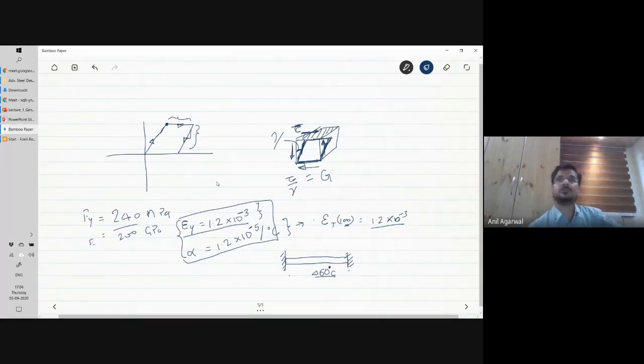While this is true, of course, we did that, and these numbers are not unreasonable. I mean, 240 is slightly small, but it just made our calculations easy. Otherwise, I could have taken 250, which would not have changed things too much. A 100 degrees centigrade change can bring the material to complete yield, and we do see up to 60 degrees centigrade temperature change all the time, right?